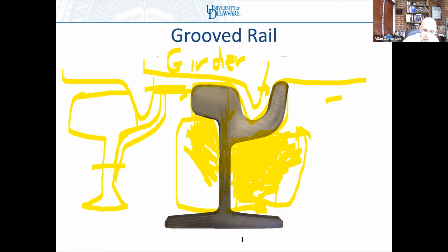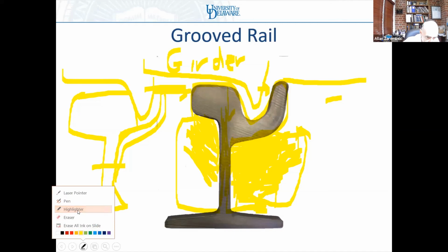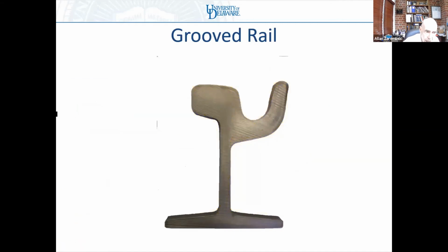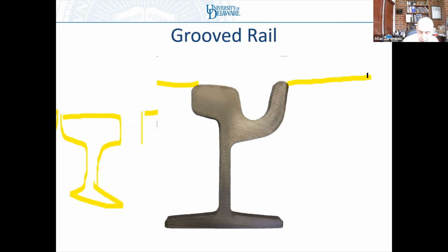in most concrete slab applications, let me clear this, draw a picture. In most concrete slab applications, there's no problem leaving a gap for the wheel flange. The problem is an embedded track, where you expect to have people walking, where you expect to have bicycles, where you expect to have some sort of pedestrian traffic. You don't want a gap at the edge of the rail.